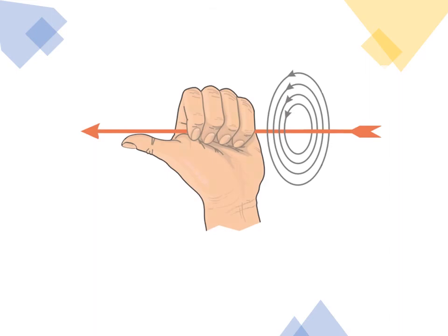We can determine the direction of the magnetic field, or the polarity of the magnetic field, around a current-carrying conductor by using the left-hand rule for conductors. Since we are doing electron flow, where the flow of current goes from the negative terminal to the positive, we use the left hand. If you are doing conventional current flow, where the idea is that current flows from positive to negative, you need to use your right hand.